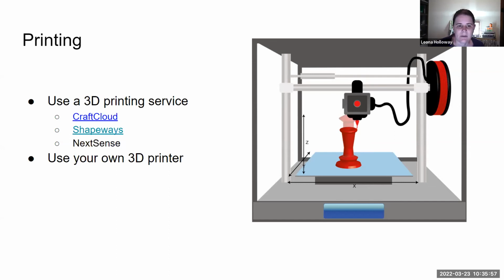But of course, 3D printing services are going to be more expensive than doing it yourself. So if you do want to take this on a more regular basis, then there are a really wide range of 3D printers available. But we do find that FDM printers, which is the one that we showed working earlier, it's the most common type and it uses melted plastic. It's suitable for most jobs, and it's also cheaper to buy and to run as well in terms of materials. So it's an excellent option. Even if we have better printers, we usually use the FDM printers most of the time.